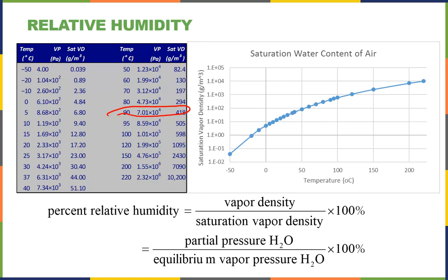For this reason, weather reports always talk about the relative humidity, though it's really not the best thing to measure. What's best to measure is what we call the dew point. The dew point tells you the temperature at which you would have 100% humidity. If the dew point goes up, that means you have more moisture in the air. Dew point goes down, you have less moisture in the air. So you can use the dew point to calibrate how much moisture is in the air.